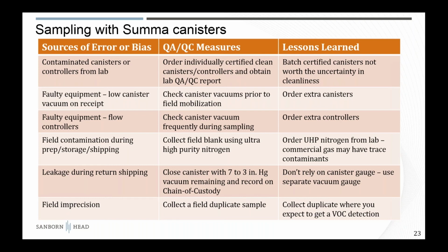They go from one site to another site to another site, and the labs have great procedures to decon them, but there's usually a choice between getting batch certification of cleanliness or individual certification of cleanliness. Highly recommend getting individually certified clean canisters and obtaining the lab QAQC report to document that the cans you received are free of the VOCs that you're going to be looking for.